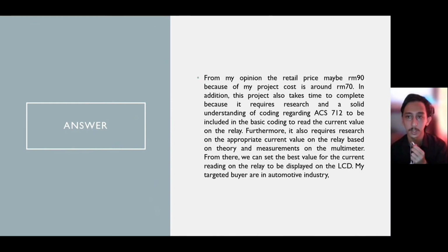Furthermore, it also required research on the appropriate current value of the relay based on theory and the measurement on the multimeter. From there, we can set the best value for the current of the relay to display on the LCD. Next, my targeted buyer is the automotive industry, so it will be easier to detect the condition of the relay, whether it is good or bad, to replace on the car.